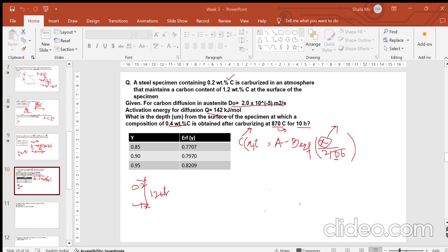Then we have another question that says, what does the eutectic phase diagram tell us about the behavior of a binary alloy? Okay, so you have a eutectic phase diagram. The eutectic point is where we have a point which is the melting point of an alloy or a mixture of two phases, which is lower than their individual melting points.